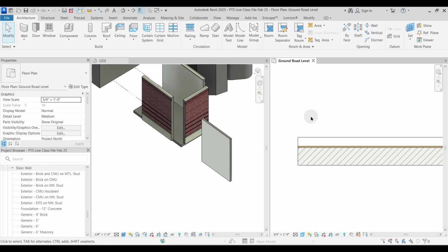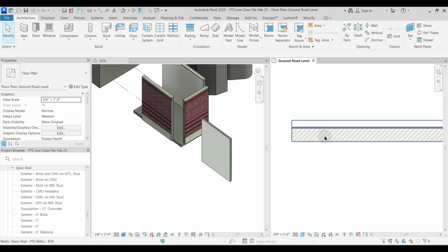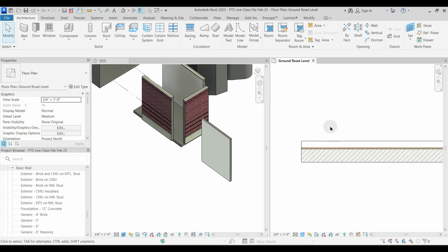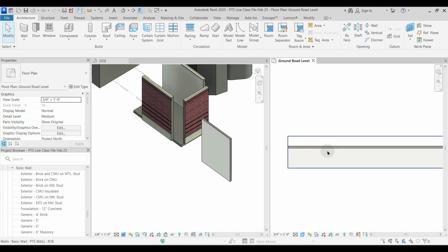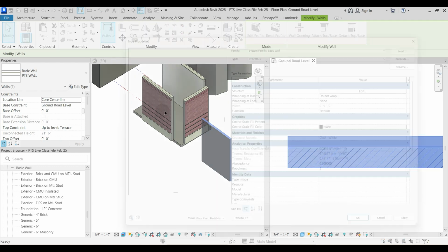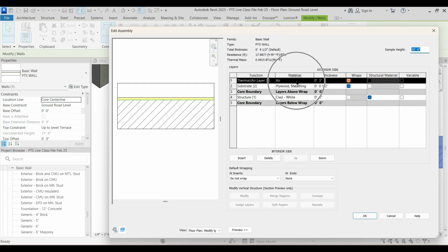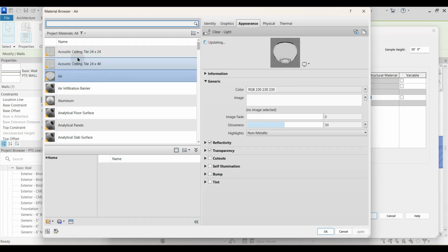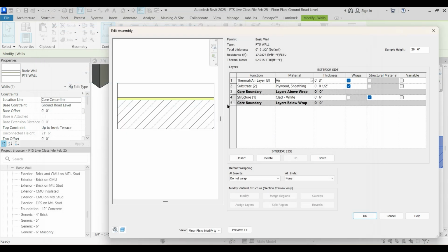If it is serving any special purpose, a special type of wall you have to design, wherein you have to control the outside moisture penetrating into the building, at that time you use this cavity layer. That is called thermal air layer. If this is the wall of an auditorium, then this particular material will change to a material having acoustics, which will provide insulation. The purpose of this particular air layer is to provide insulation, whether heat or cold insulation or sound insulation.